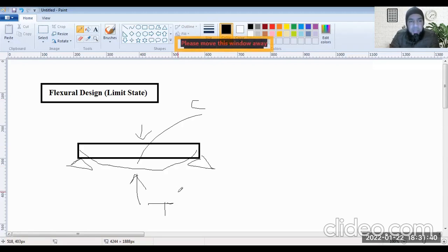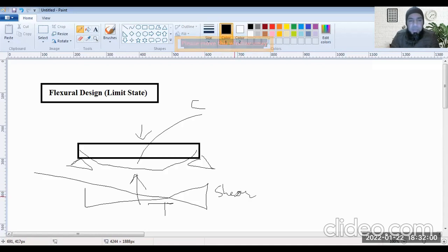So flexure becomes a very good property to study first, because it shows parts of compression, parts of tensile behavior, and to accompany this, there will always be shear in this beam. So you can also study the shear at the same time. That's why we start with beam designs, because they give you an idea about all the three: compression, tension, and shear, which are the predominant ones. And for the limit state of serviceability, it also shows the deflection profile. So beams are the first elements that we usually study in flexural design.